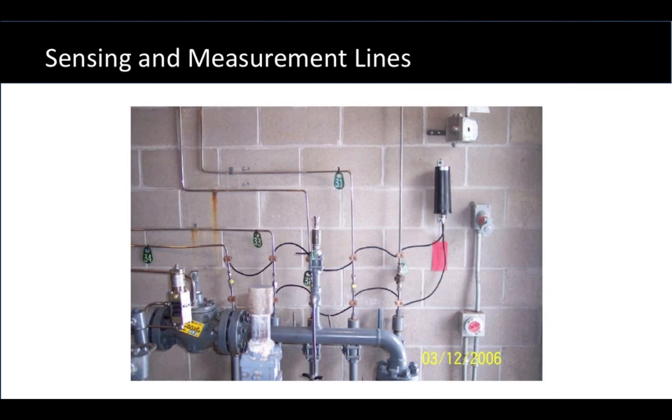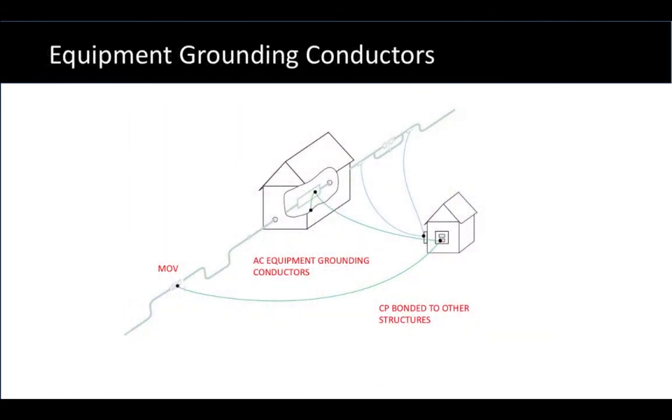Here's a pictorial of an insulated joint set where the measurement tubing in a series of 5 parallel lines all have been decoupled with a single decoupler. That's the black cylindrical looking object to the right, and they've all been jumpered across with cables so that one device protects this combination of 5 insulated joints and does so successfully.